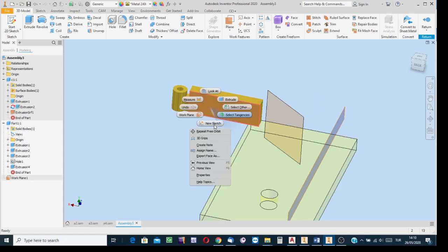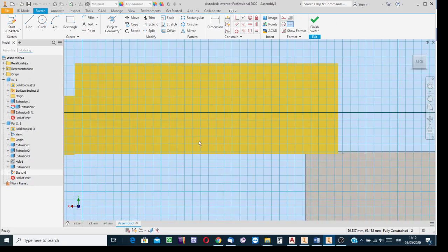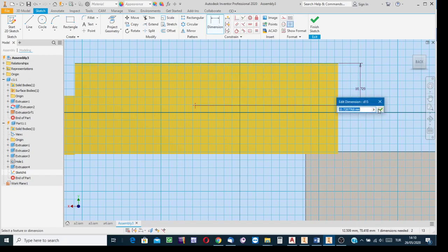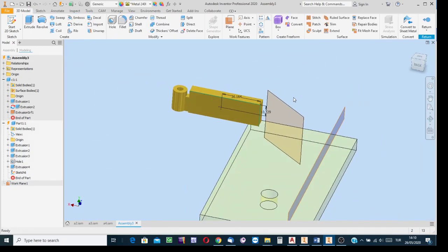First, over the surface, mark the piercing point for that imaginary axis. Okay, mark the point, and then dimensional constraint. From this edge of the surface to this point, the distance is equal to that much. From this edge of the surface to the point, the distance is equal to that much. Okay, position the point. It is the piercing point for the axis.